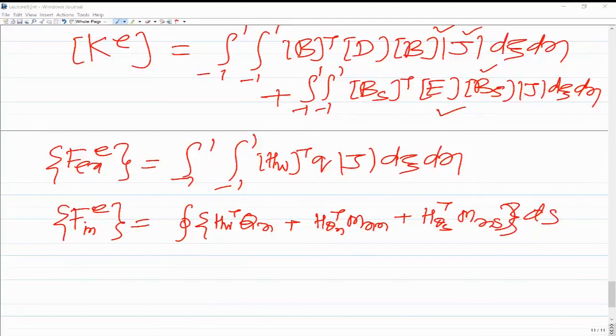So that is already a rectangular element in the physical coordinate space, but still it is not compatible. So even if you go to natural coordinates, the same situation will be there. If the primary variables involve derivatives of the basic variable, then it is difficult to achieve compatibility without introducing additional degrees of freedom. But if no derivatives of the variables are involved as primary variables, then you can get the compatible element by doing the formulation in the natural coordinate space for the corresponding arbitrary quadrilateral in physical coordinate space.